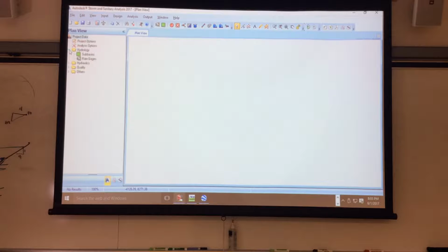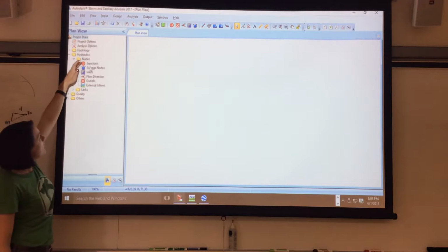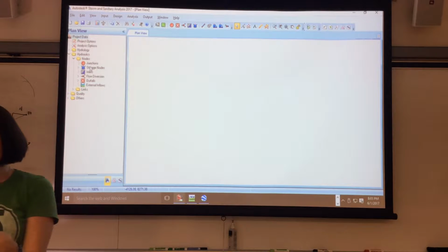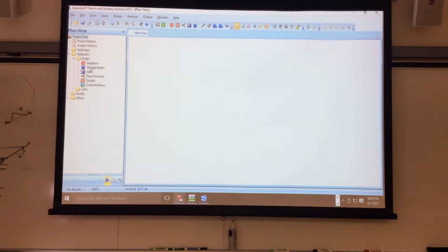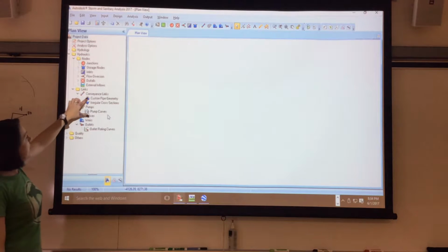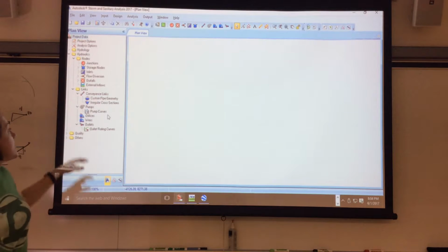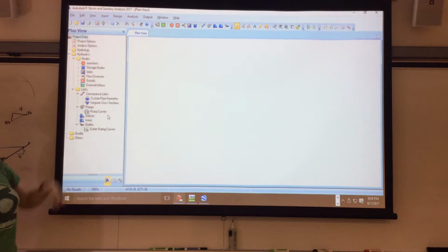Now, you also have the hydraulics portion of it. And the hydraulics portion, I'm going to collapse these. The hydraulics portion has to do with nodes and links. A node is a pond or a basin, and a link would be your structure, a pipe, a control box. So you can see that it's a conveyance pipe, a regular cross-section, maybe a ditch. It can also be pumps.